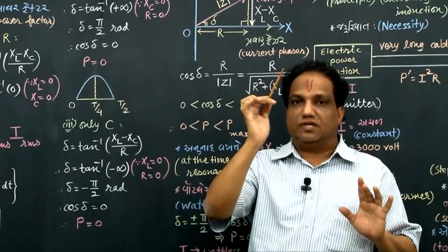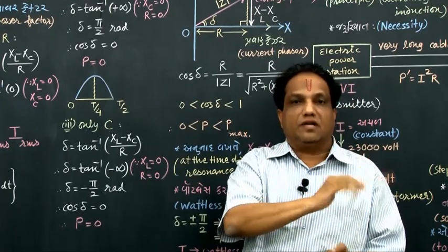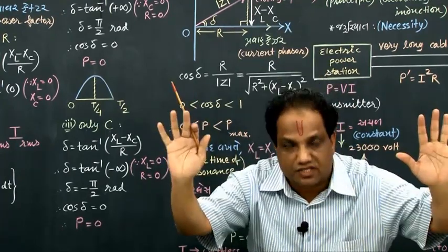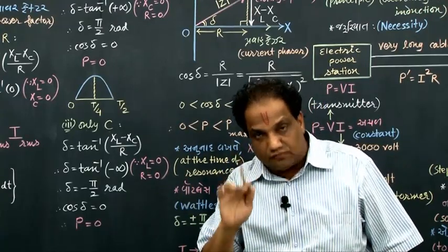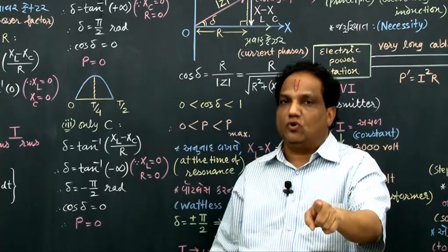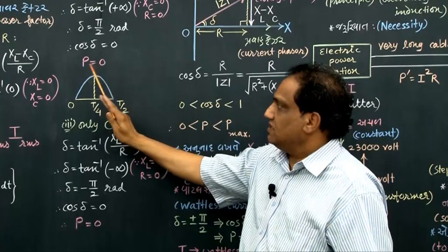During increasing current condition, inductor receives the energy. During decreasing current condition, inductor loses that energy. So, net amount of energy spent in such circuit is 0. When net amount of energy spent is 0, naturally power also will be 0. That is why power is 0.